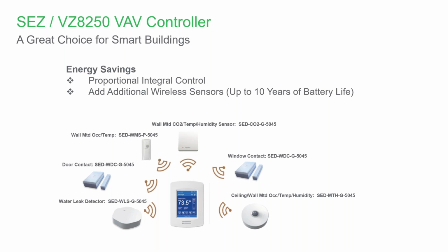Instead of having one temperature sensor that takes that input from all of those zones, all those folks that are out there, you can install these occupancy/temperature sensors and be smart about averaging temperature, not just an average of all of them, but an average of the ones that are occupied. So that's one of the benefits that we see folks using the Zigbee devices on this product the most.